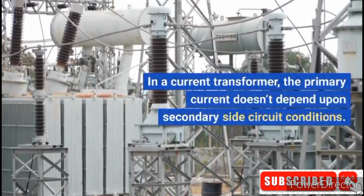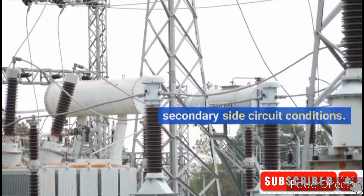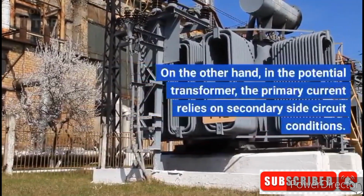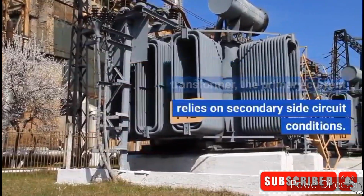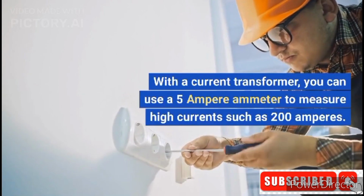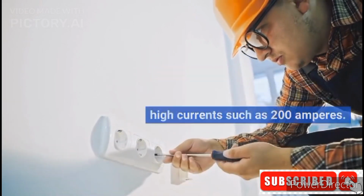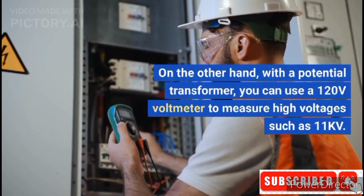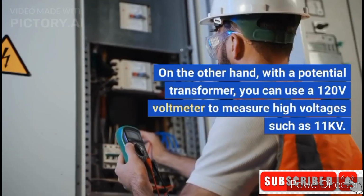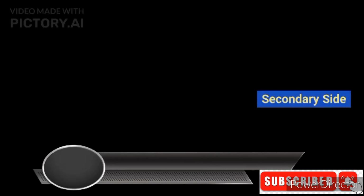Primary current. In a current transformer, the primary current doesn't depend upon secondary side circuit conditions. On the other hand, in the potential transformer, the primary current relies on secondary side circuit conditions. Use. With a current transformer, you can use a 5 ampere ammeter to measure high currents such as 200 amperes. On the other hand, with a potential transformer, you can use a 120 volts voltmeter to measure high voltages such as 11 kilovolts.